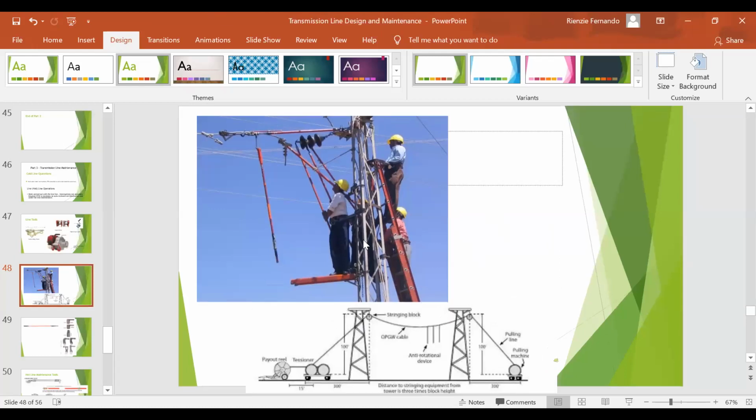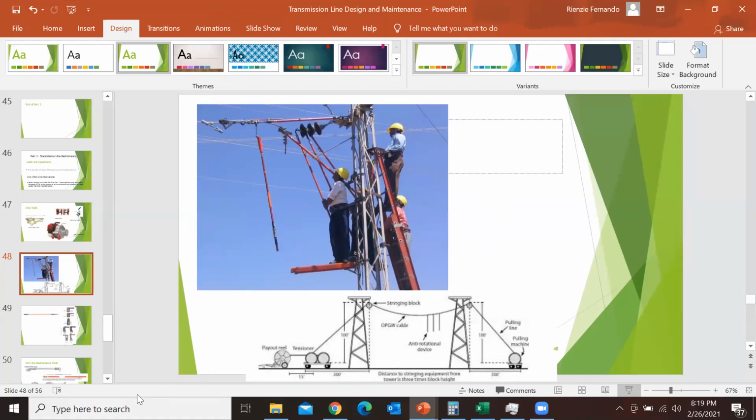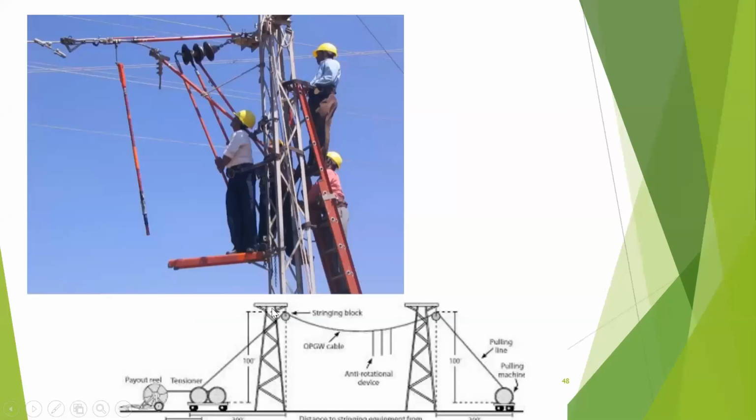Now, when you are conducting a line, say from one tension tower to another, you are stringing. Here you keep the tensioner, and on the other side you keep the puller. So you pull it, and if the puller stops with the speed of the drum, you can't control it if the tensioner is not there.